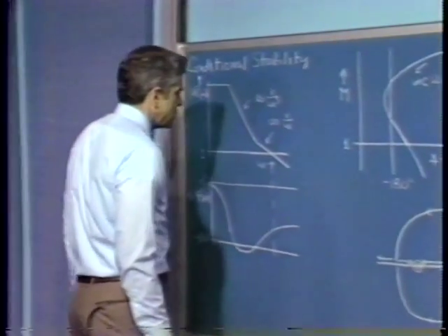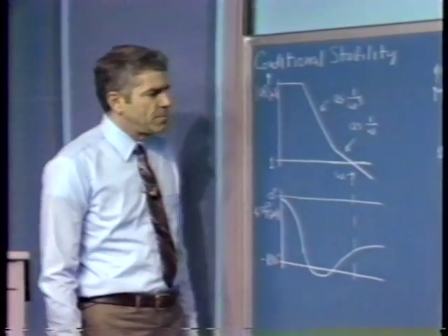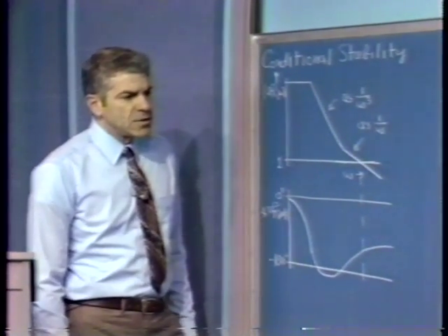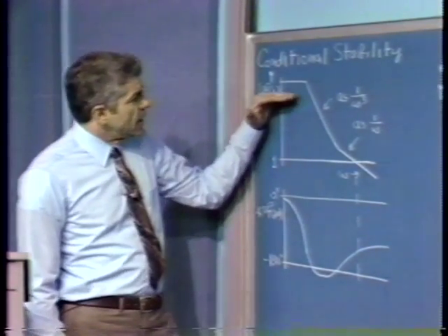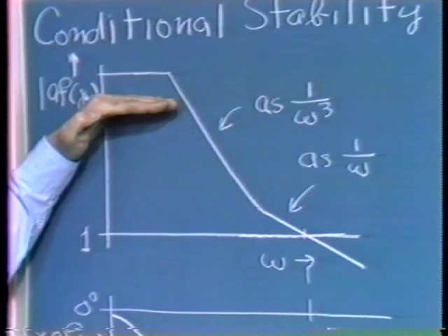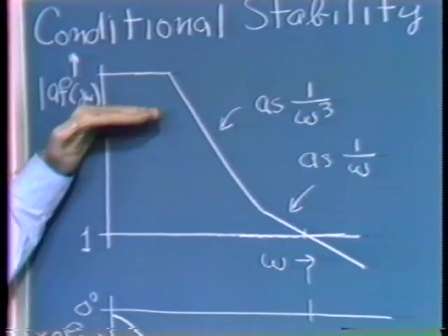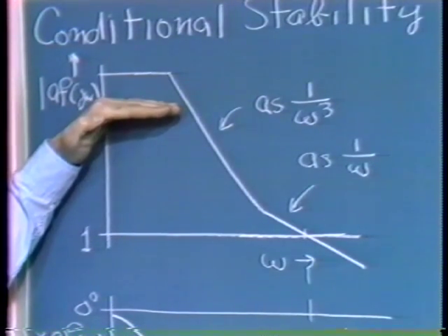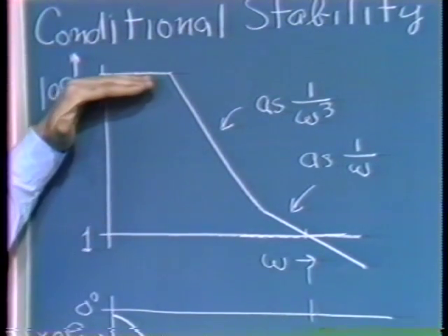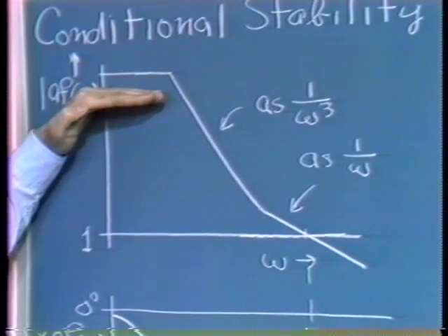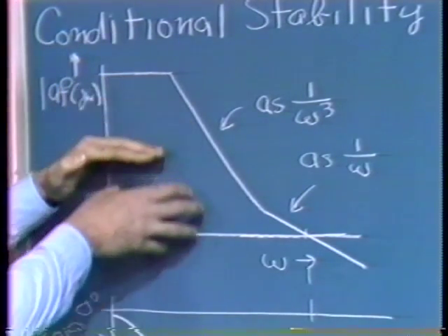Consider what happens if the amplitude of the signal applied to the nonlinearity is such that we're into the saturating region. And if we now consider this to be a plot of the negative of the loop transmission for a nonlinear system, where we, of course, get the gain of the nonlinearity via our describing function analysis, we'd find that operating in saturation shifted the curve down.